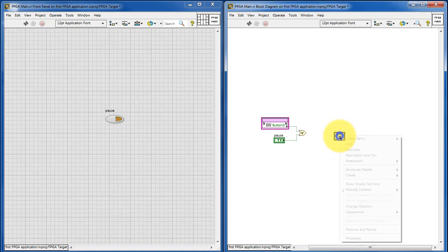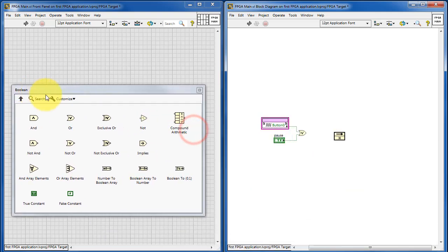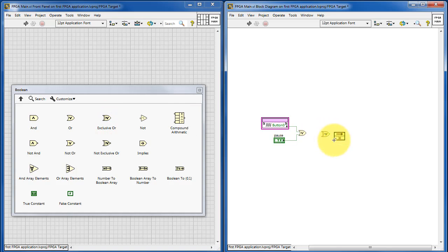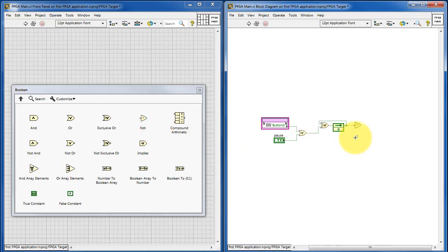I'm placing a feedback node, and especially when you flip the direction like this, you can now view this as a flip-flop, because that's what it will be on the FPGA fabric. The exclusive OR serves as a selectable inverter. So we take the present state of the flip-flop, feed that back around, and then depending on the second input of the XOR gate, it will allow the output of the flip-flop to toggle or to remain in the same state.